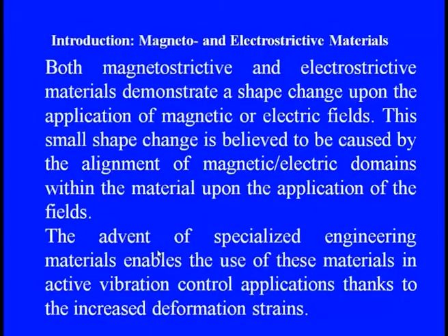The small change is believed to be caused by the alignment of the magnetic or electrical domains within the material upon application of these fields. The advent of specialized engineering materials enables the use of these materials in active vibration control applications, because of the increased deformation strains. When the change in shape or strain occurs, we can judge how much energy suppression or force application is taking place.